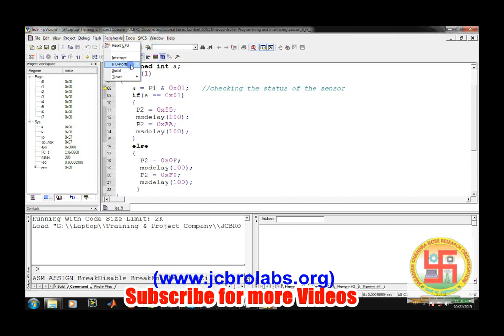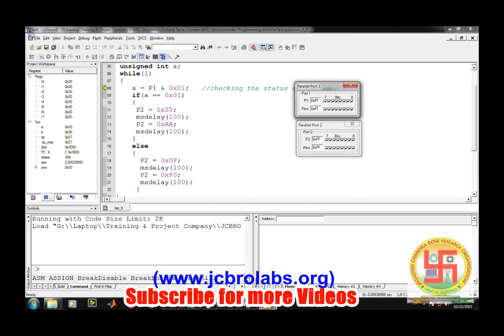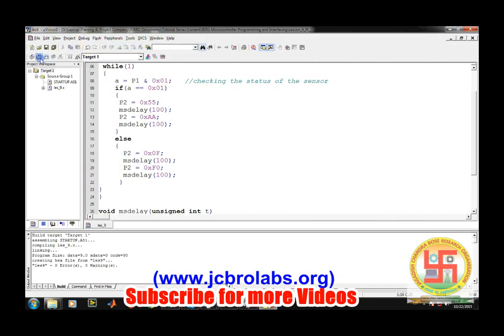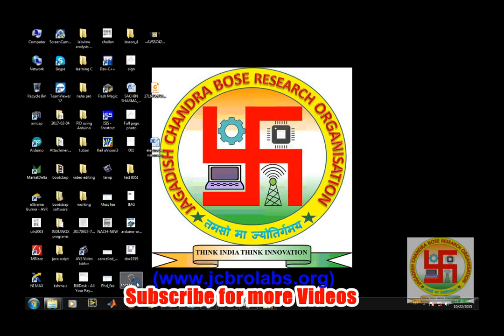Let's open the ports because we have two ports. Port 1 is connected, so let's say we step one by one, we set it to 1, and the LEDs will turn on alternatively. And let's make it 0. So it should go into half of the LEDs, and half of the LEDs will turn on, and it will do it continuously. So it's working fine in this debugging section. Let's stop debugging, and now let's burn the same hex file into the microcontroller.